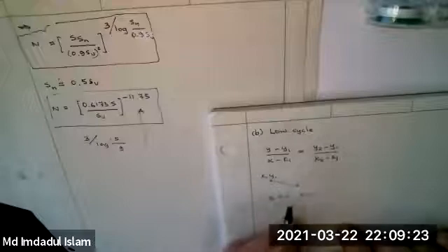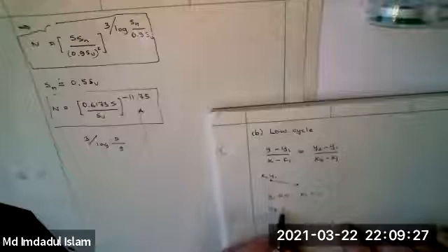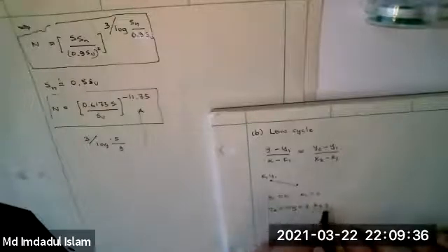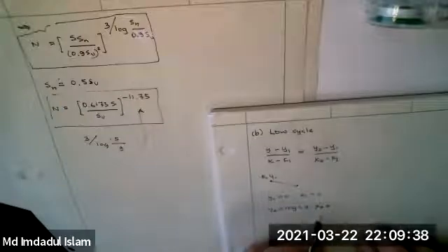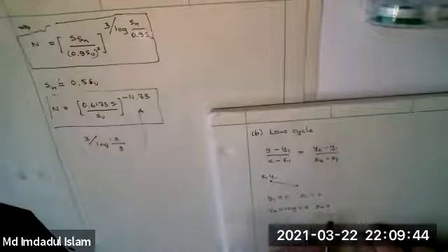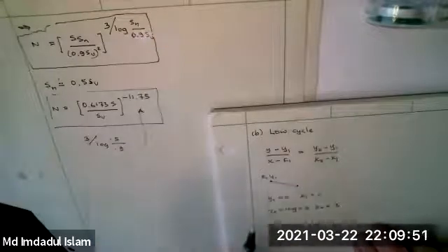And this one here was back to Y2. Y2 is 90% of S, S was 90% of SU, so it's log of 0.9. And that got us 10 to the 3 cycles. Okay. So Y2 X2 used to be Y1 X1 in the previous fit.